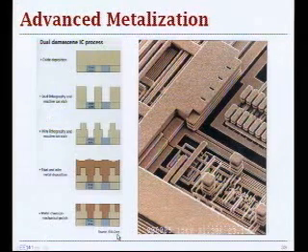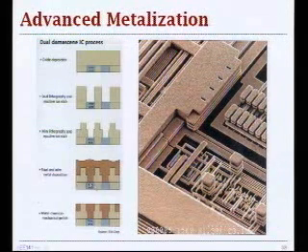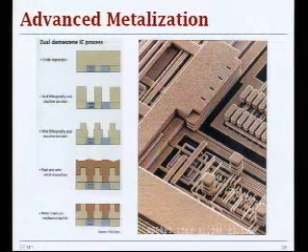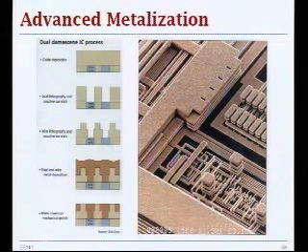This was in '98, and now more and more processes use copper metalization, where you can basically just fill your metal into these trenches, and then you do mechanical polishing on top to even the structure, and then you can continue building up. But although it seems really complicated, for each of the layers you have basically a bunch of predetermined sequence of steps that you just go around